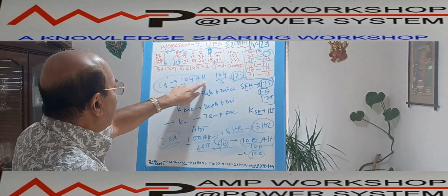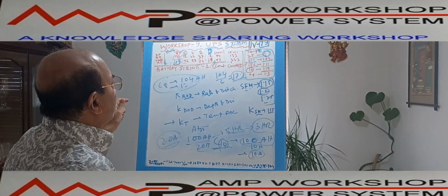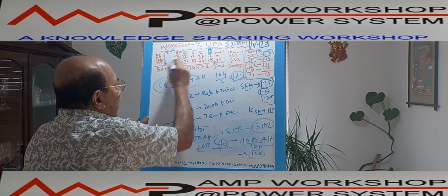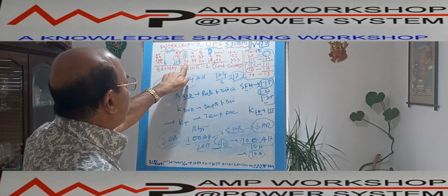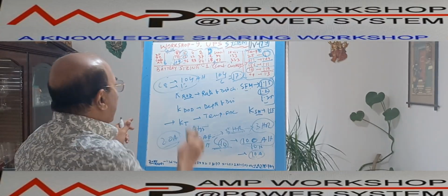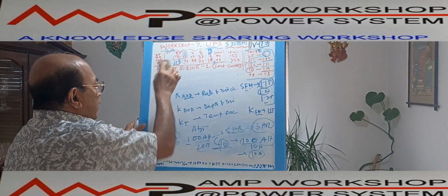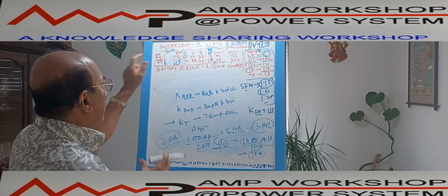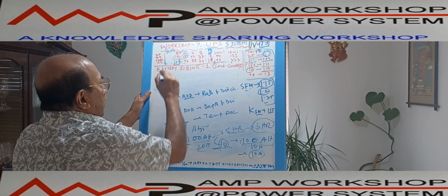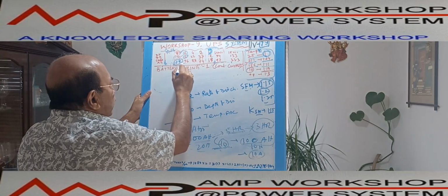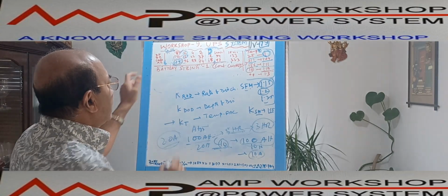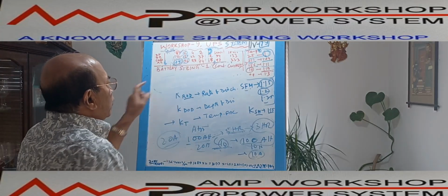If it gave in proportion, but no, you see it is giving only 16 ampere and the corresponding ampere hour is 96. That means the battery which is rated for 104 ampere hours at the rated condition, the moment I increase the current from 13 ampere to 16 ampere, instead of giving 104 ampere hour energy, it is giving only 96 ampere hour. So there is a reduction.